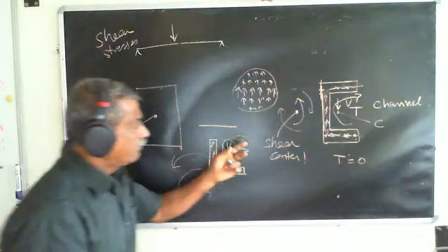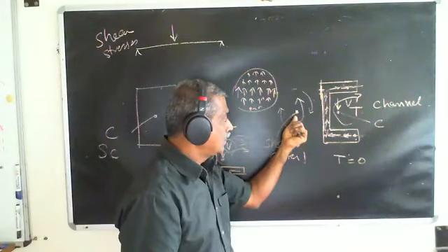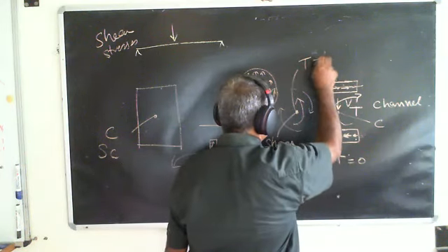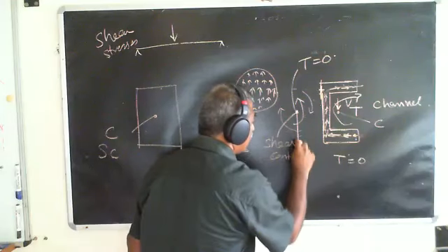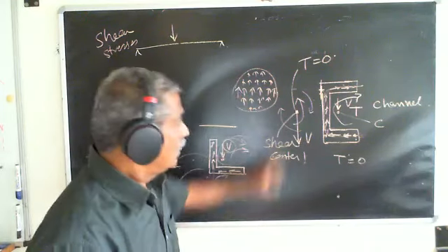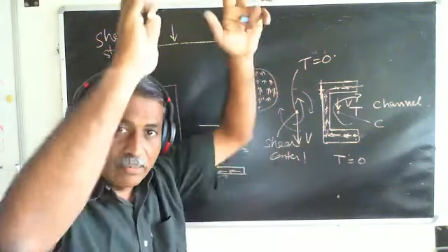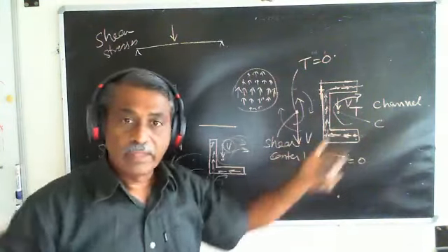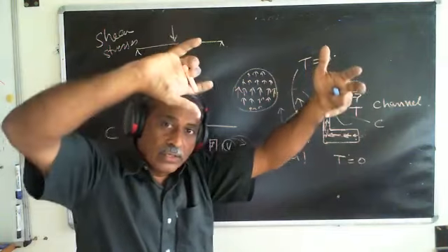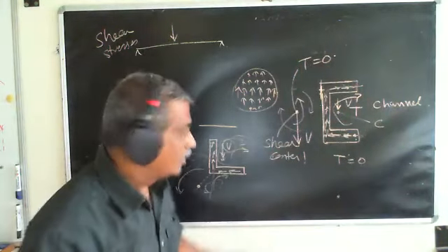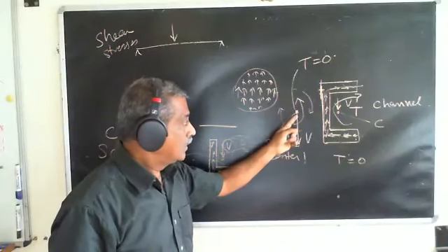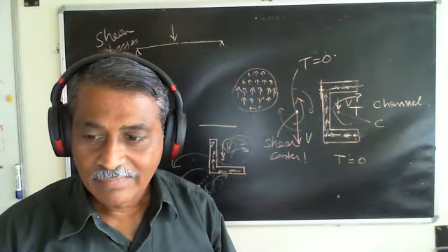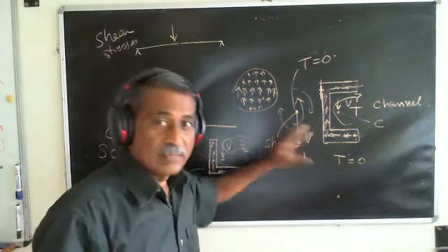Right? But the fact of the matter is I have a center of the twisting moment that is equal to 0. At this, the twisting moment is 0, and therefore if I apply the transverse load alone, it will retain that particular orientation of that section throughout the beam. If not, what will happen is this orientation of the cross section will start to twist. Are you with me? Right? And that's how we find out the shear center. Got it? This is another concept that you should know.